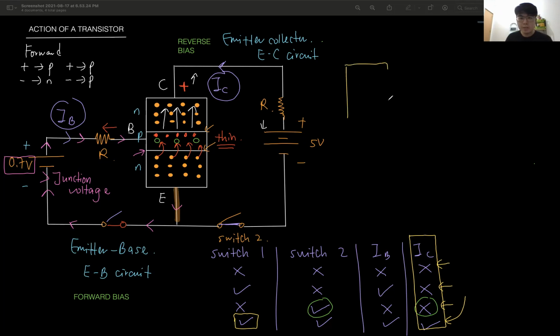This is your transistor, NPN. When you turn on the two circuits, let's say we have 100 electron come in. 100 electron diffuse into the p-type. Because the p-type is only lightly doped, it contains only a few holes. Let's say only one, meaning that only one electron can recombine and flows back into the circuit.